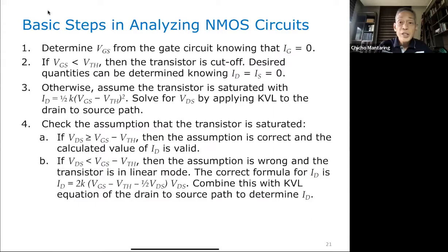We usually assume first that it is in saturation, because the saturation equation only depends on one variable, that is VGS, so the computation is going to be easier.